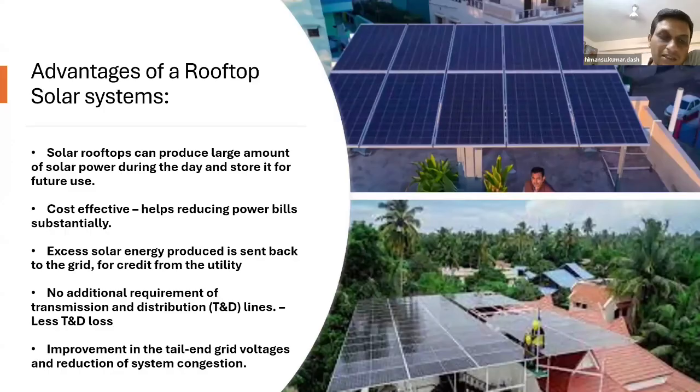So if you can imagine a situation, if the majority of the consumers who have feasibility of rooftop solar installation produce what they consume, then automatically this low voltage issue will not be there. That means the active and reactive power demand by the households can be generated by them, and in turn this will reduce the kilowatt and kilovar loading, the MVA loading. It will reduce the loading of the utility. So these are advantages.